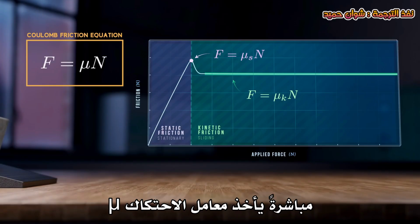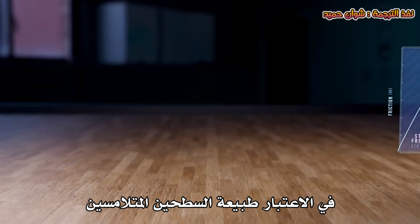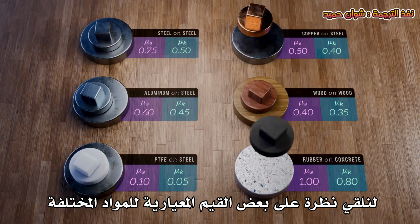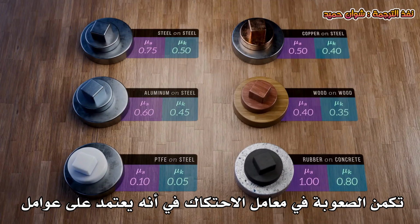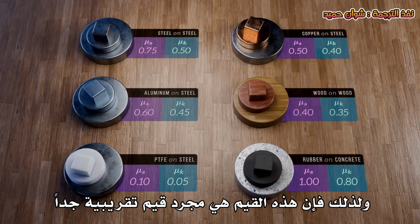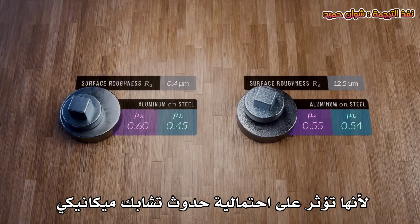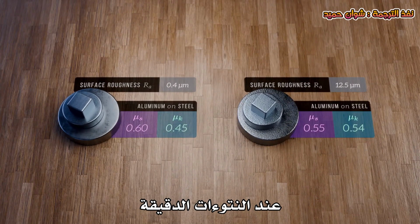The coefficient of friction mu accounts for the nature of the two contacting surfaces. Let's look at some typical values for different materials. The difficulty with the coefficient of friction is that it depends on much more than just the materials involved, so these are all very approximate values. Surface roughness has a big impact because it affects the likelihood of mechanical interlocking at asperities.